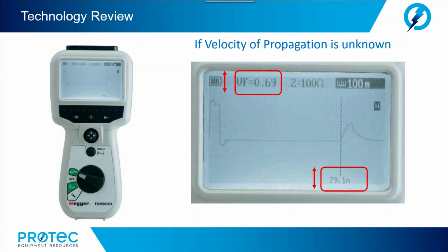The TDR now has enough information to calculate where the event is, like our trip from Dallas. It knows how long the pulses and its reflections traveled, and it knows how fast the pulse was going. The TDR merely must do the arithmetic.